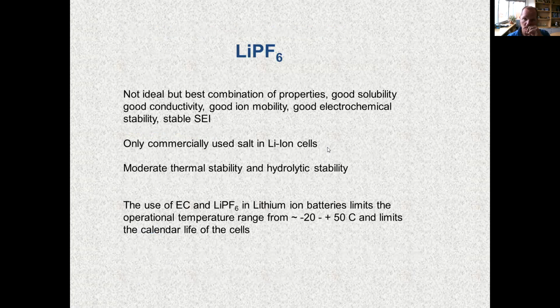That brings us to the salt that is the most widely utilized commercial salt, LiPF6. LiPF6 is not ideal, but it has the best combination of properties. It has good solubility, good conductivity, good ion mobility, good electrochemical stability, and stable SEI. It's really the only commercial salt used in lithium-ion cells.